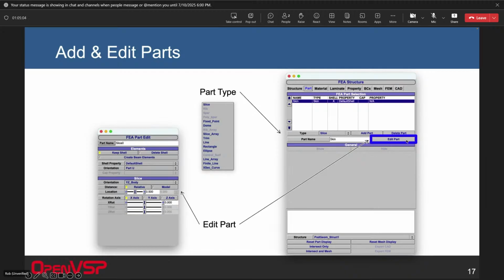And then to really drill down, you click on Edit Part, and Edit Part will pop up, and all the parameters for that part will be displayed, including up here at the top, everything is always the same. So on a part, you can just say whether you want to keep the shell elements or delete the shell elements, and then whether you want to create beam elements. So if you have, for example, a rib on a wing, the beam elements will be created at the intersection between that rib and the wing. So that intersection curve becomes those beam elements.